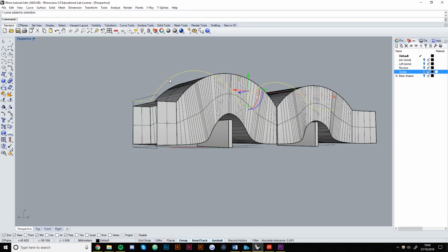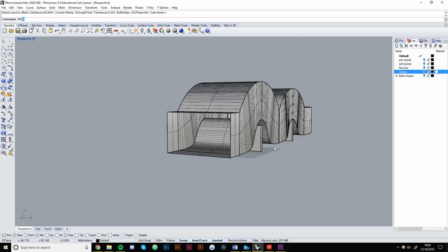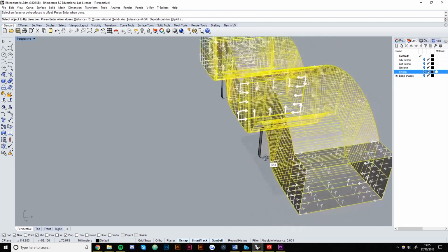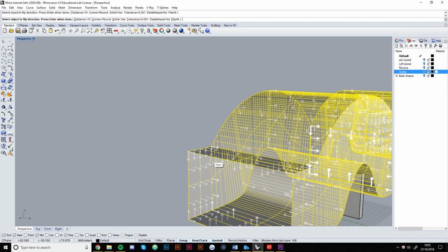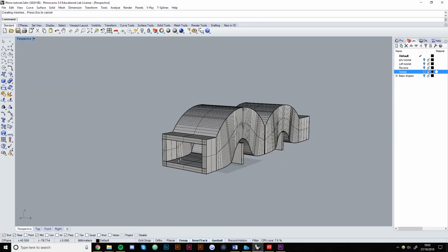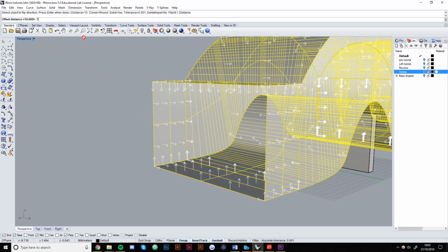And then I'm just going to delete these curves because we don't need them any longer. And then we're just going to offset surface, sorry. If you type offset surf, you can then click on our poly surface and hit enter. All of the arrows should be pointing towards the inside. If they're facing out like this, just click anywhere on the form and it's going to flip them. And then just set the distance at something like, say 10. Just maybe a little thick, so we can redo that with, say 5.